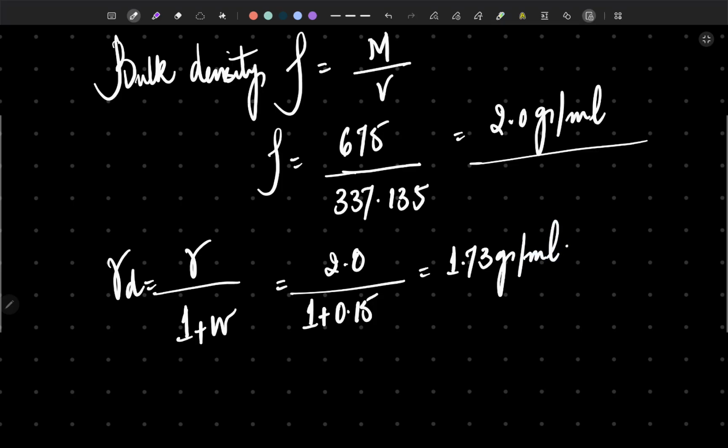Pay attention to the data as given in the question. This was initially based on the water displacement method for finding the bulk density, or the mass density. Then the sample was subsequently taken for some other test to find the water content and the specific gravity as well. So I have found the dry density. Now my aim is to find actually the void ratio.